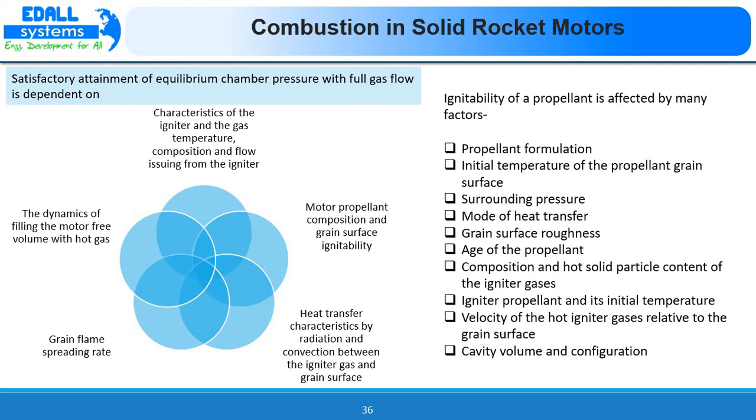If any of these factors have a significant impact on the ignition, then the equilibrium chamber pressure won't be achieved, and there will be some abnormalities which will cause combustion instability. So one has to be very familiar with all the factors which affect the ignitability of a propellant and has to take care of such factors to avoid them, using some solid propellant ingredients which we have discussed earlier.